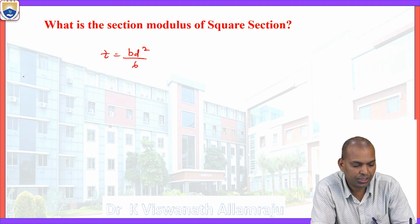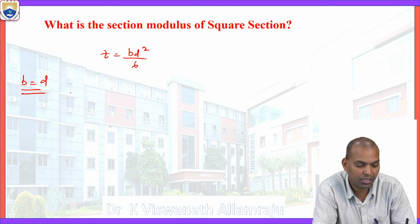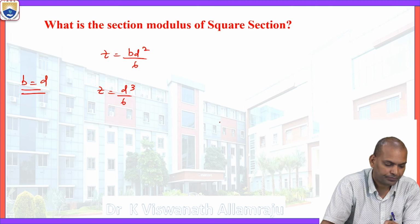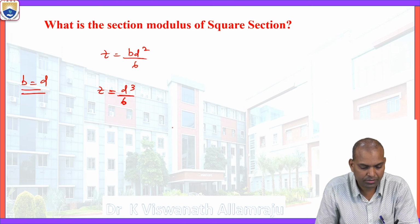If we want a square section, in the square section, width equal to depth. All sides are equal. Then it becomes d cube by 6. Z equal to d cube by 6.